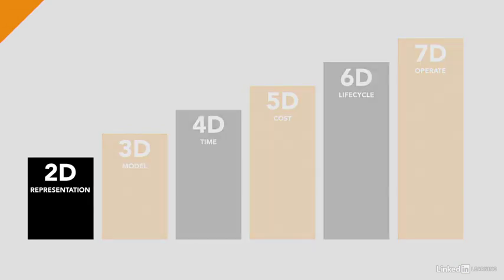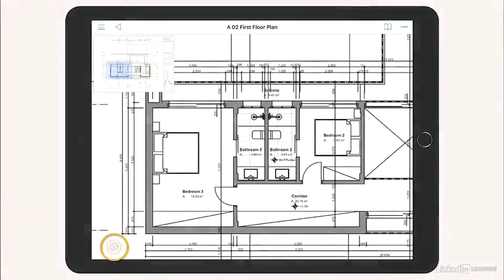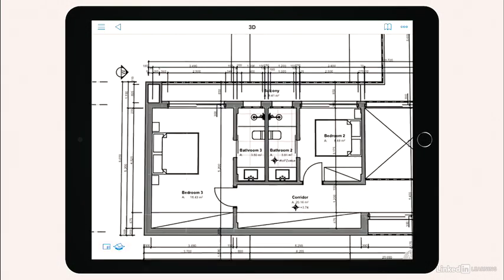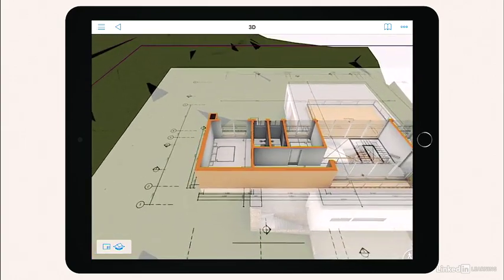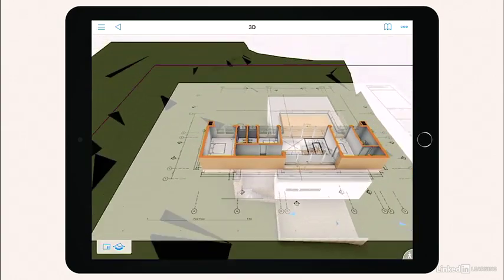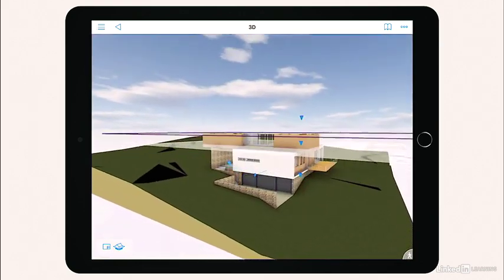I guess you were surprised to hear about 2D BIM. 2D hasn't disappeared yet, but there is a difference between 2D BIM and 2D CAD. All 2D plans, sections, and elevations are extracted from the 3D BIM model. Otherwise, it would mean you are duplicating effort and data in creating original 2D drawings, which is not an ideal workflow. Lots of firms who are transitioning to BIM have the tendency to start on CAD and then subcontract the creation of the BIM model.